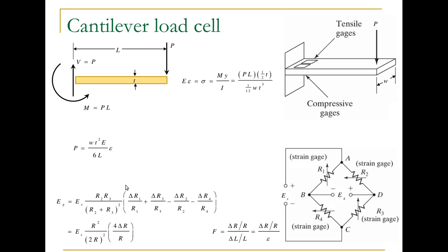Now, if all 4 of these strain gauges are identical, then their unstrained resistance values are identical, and their gauge factors are identical, so their changes in resistance will be the same. Well, the two on the top will have the same positive change in resistance, and the two on the bottom will have the same negative change, which is just the same as the top multiplied by -1.